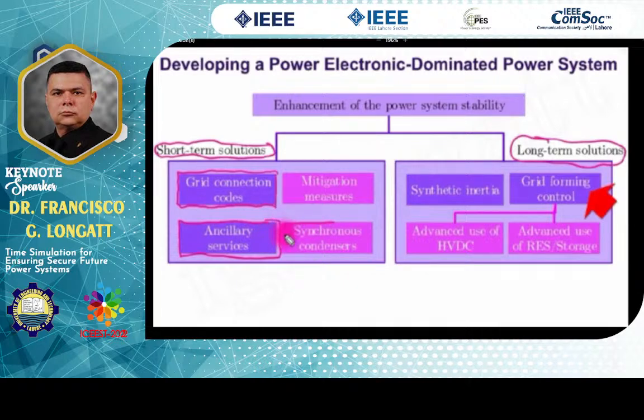In some other countries, we already defined that we need to take some short-term solution. For instance, in the case of the UK, the short-circuit currents are decreasing quite fast. And one very simple way to produce short-circuit contribution is using what we call the synchronous condenser.